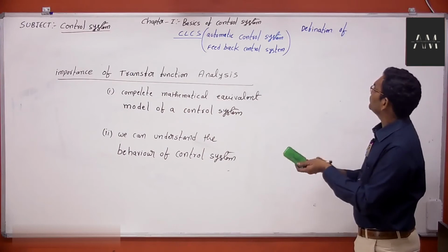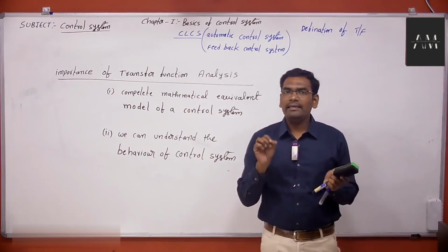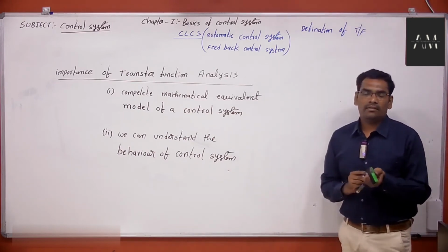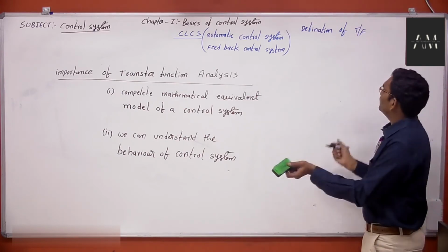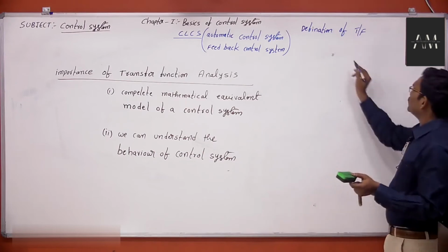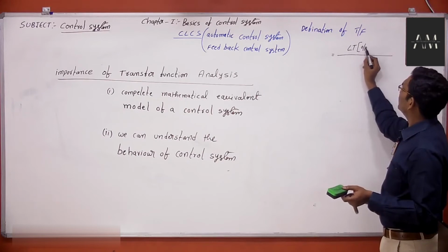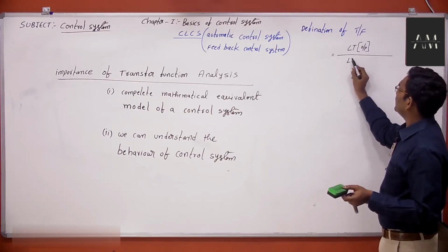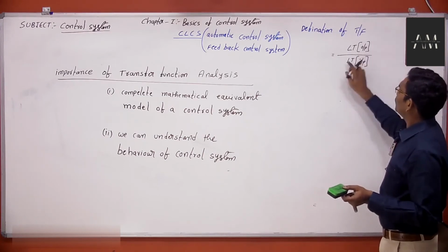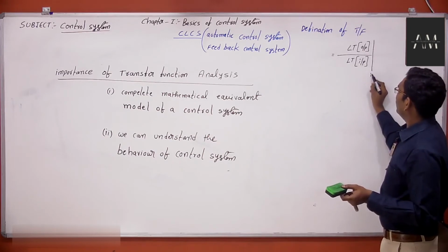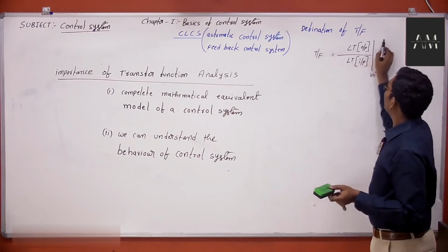Now what is transfer function? See here, for a linear time invariant system, take down the definition. For a linear time invariant system, the transfer function is defined as the Laplace transformation of output to the Laplace transformation of input with all initial conditions equal to 0. This is the transfer function definition.